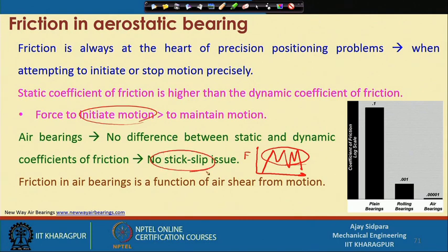So, this is called the stick and slip phenomenon, which mostly happens when you want to rotate something by hand. If you consider your carriage, when you want to penetrate your tool into the workpiece and you are moving it by a wheel, with a circular handle, at that time you will feel the stick slip phenomenon in the machining process. That is a very common issue.